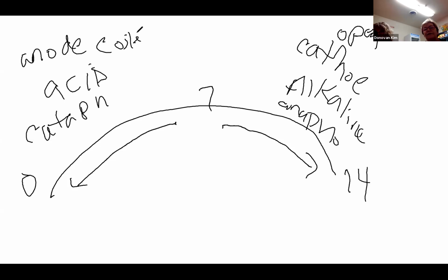The reason why I'm saying that is because the questions are put to you like this. If I'm using my anode, what treatment am I using? Am I using cataphoresis, anaphoresis, anode, or cathode? If I'm using the anode, that means I'm doing the cataphoresis. A way to remember: anaphoresis and alkaline are always on the same side. If you can remember those two, you know they're opposites. So alkaline's opposite is acidic or acid. Anaphoresis and cataphoresis are opposites.